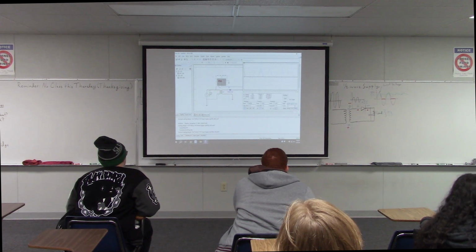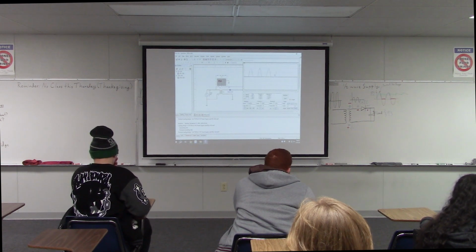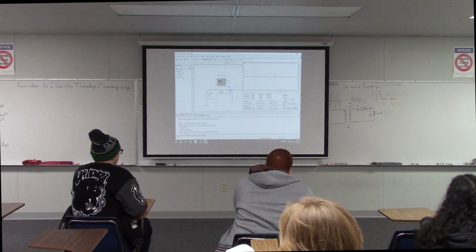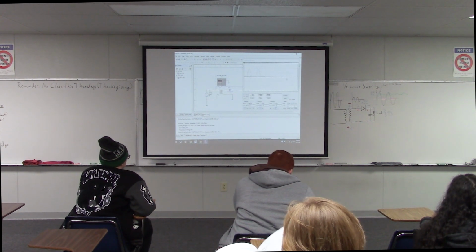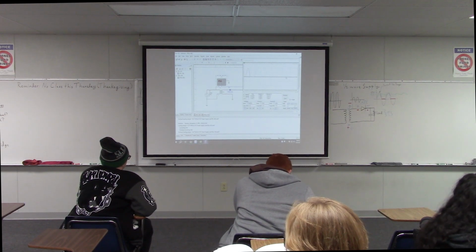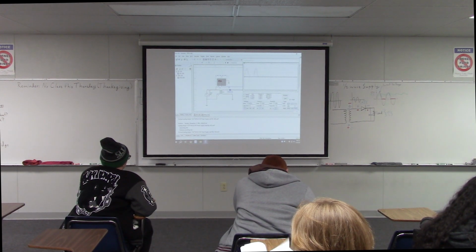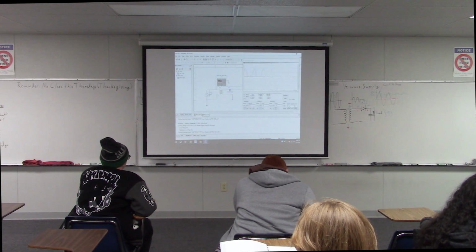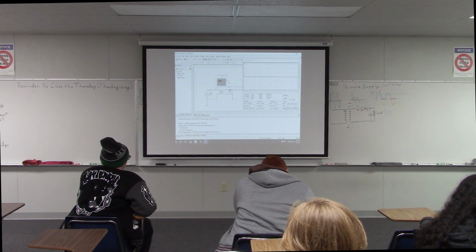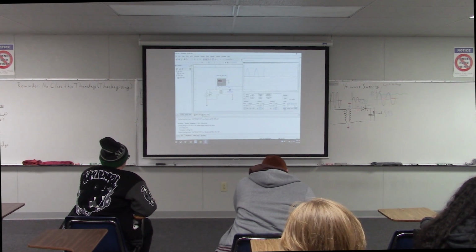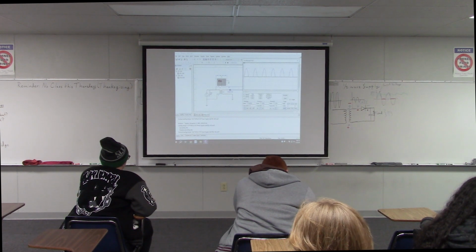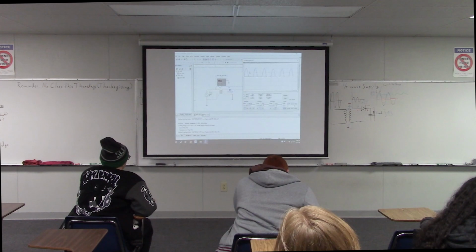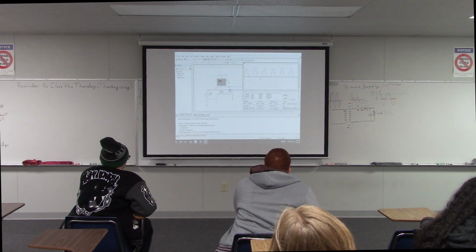Right now, the signal is bouncing around on the screen, kind of like we've seen on our oscilloscope screen. We remember that it does that when it's not triggering properly. So first of all, I'm going to set the trigger level to be single. That just means that it takes a picture of this signal and captures it on the screen.